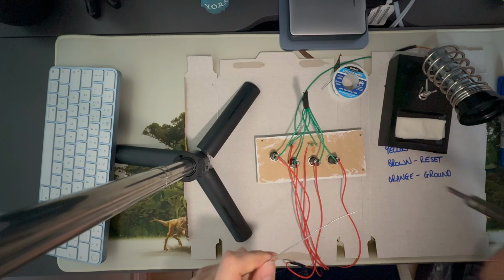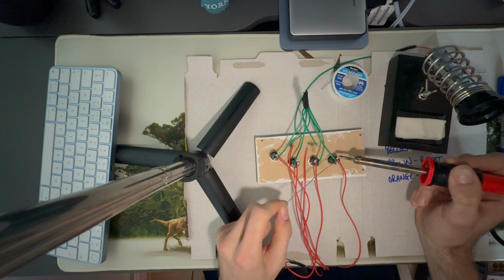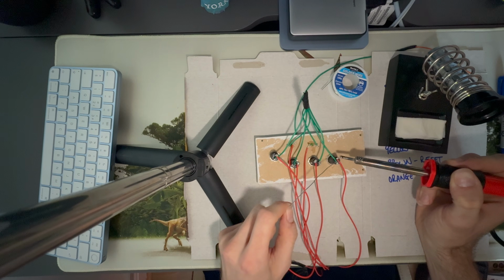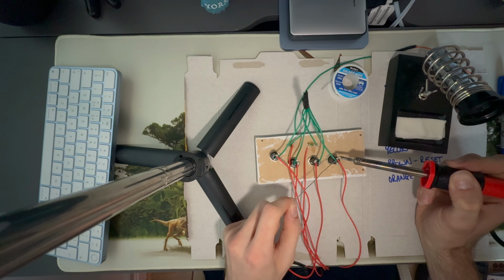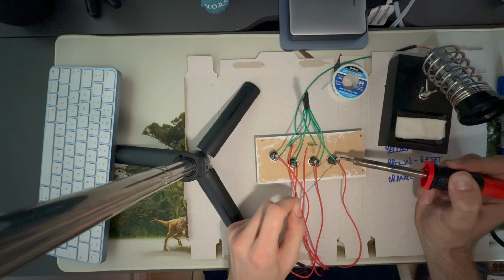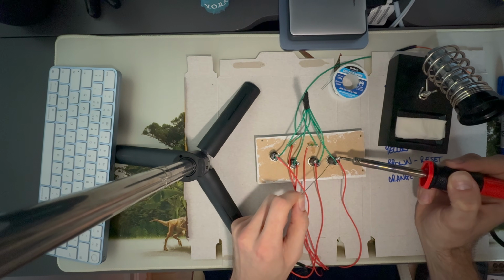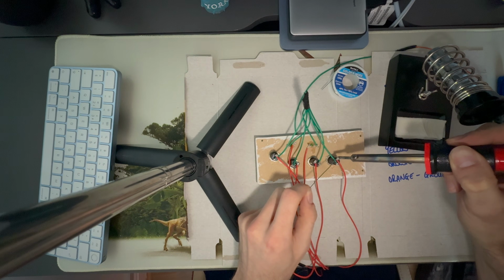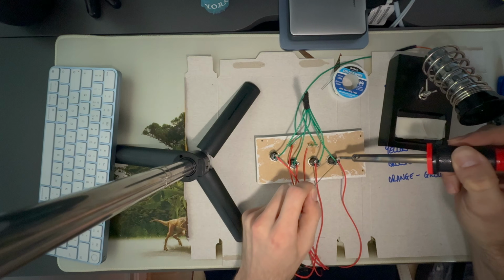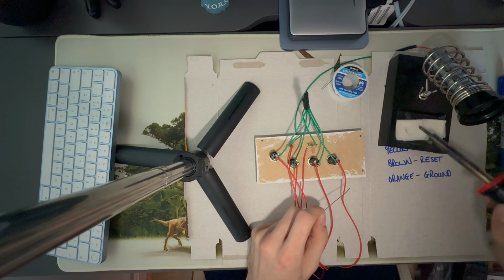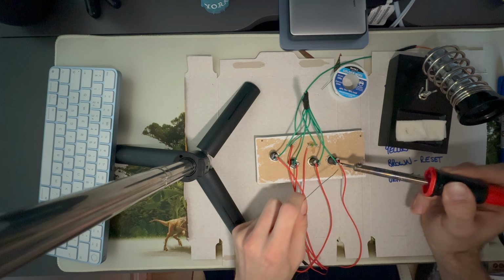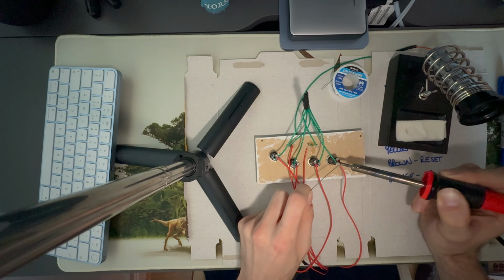And we're going to feed onto the component, just warming it up, and then slowly add in the solder. You'll see the smoke coming off it. So the soldering iron is nice and hot. You need to give it a couple of minutes to warm up. There we go, and then just clean it with a damp piece of kitchen roll or something, and continue for the rest of the components and the parts.